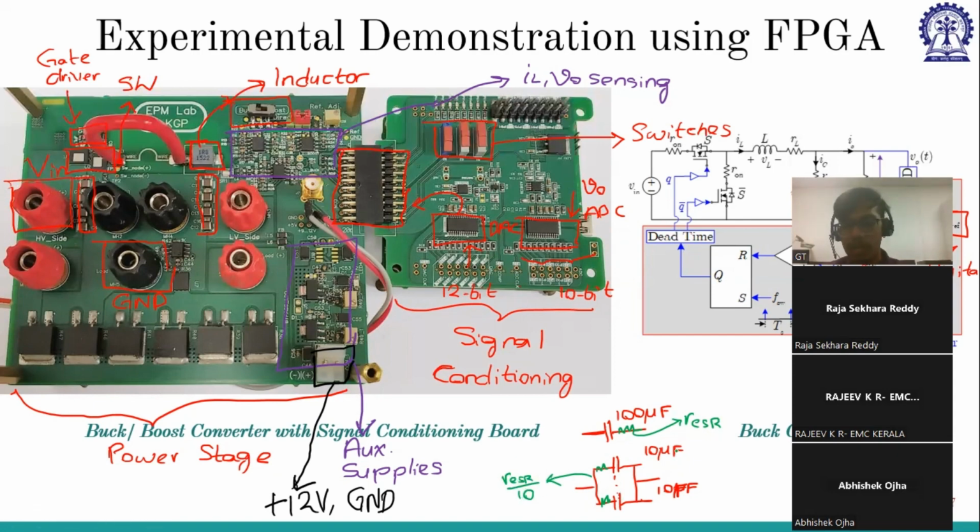Now you may ask, instead of connecting ten 10 microfarad capacitors, I'll connect a hundred 1 microfarad capacitors. But again, it comes to the space requirement, right? We cannot fully increase the number of capacitors. So there will be this space constraint as well as this ESR constraint. So we generally consider around 10 capacitors or so. I think according to the calculations they have used, if you can see there is one big capacitor and one small capacitor. I think those are of different values. The big capacitor is of big value and the small capacitor is of small value. So the effective ESR in parallel will reduce the total ESR, and the capacitance will be the summation. For that reason, we use multiple capacitors.